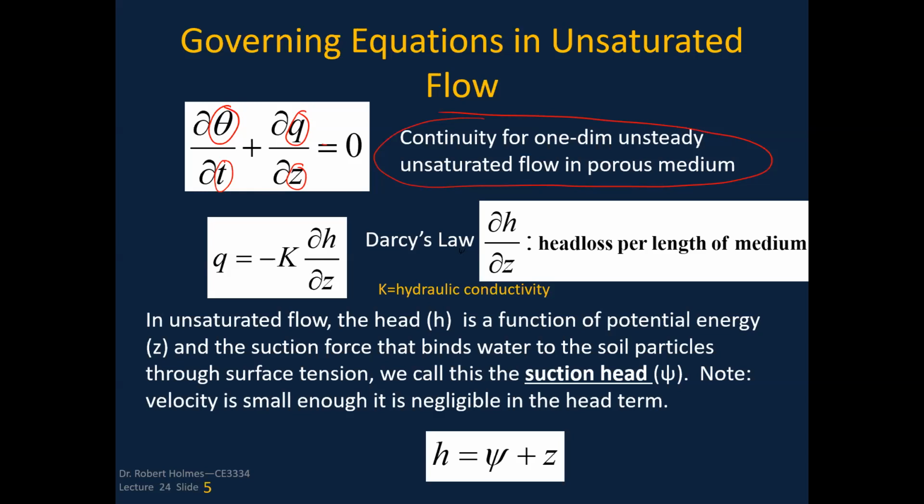Now, we've talked about the Darcy flux. I want to introduce Darcy's law, which basically is the negative value of the hydraulic conductivity multiplied by the head loss per the medium. And so the head loss is the head change over the depth, okay?